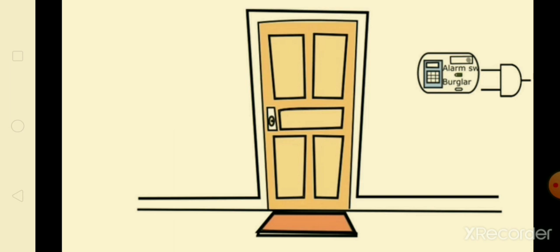So your first switch is already 1, that is high, and when the person comes inside your house, that will again turn with the help of a sensor, and that will also become 1. So 1 and 1, at that time the AND operation happens, and that will set your alarm, and your burglar alarm will start ringing. That is 1 into 1, or 1 and 1, that will give you 1, and your alarm starts ringing. So this is the popular example of an AND gate, that is the burglar alarm.